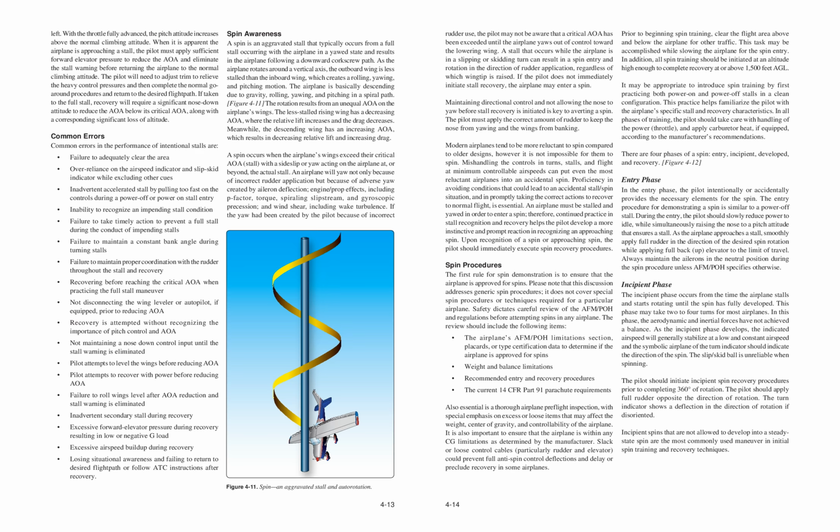If taken to the full stall, recovery will require a significant nose-down attitude to reduce the AOA below its critical AOA, along with a corresponding significant loss of altitude. Common errors in the performance of intentional stalls are: failure to adequately clear the area, over-reliance on the airspeed indicator and slip/skid indicator while excluding other cues,